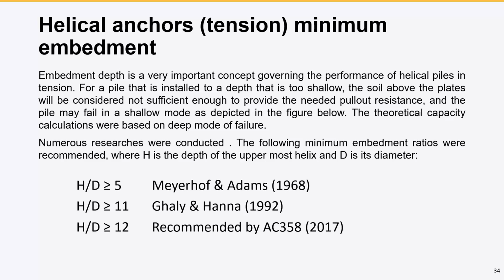Ghaly and Hanna used a minimum embedment depth of 11D. But in 2007, when AC358 was issued, we came up with 12D minimum embedment depth. And all these helical pile manufacturers who have their ICC reports tested by CTL Thompson for tension, the minimum embedment depth was 12D. For example, if you have a single 12-inch helix, it has to be 12 feet below the ground surface. If you have an 8, 10, 12-inch helix configuration helical pile, the 12-inch, the uppermost helix, has to be 12 feet below the ground surface.